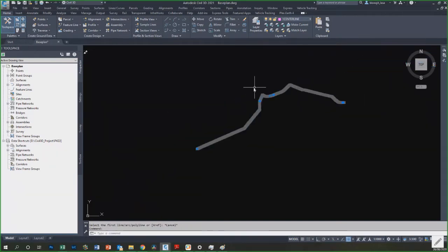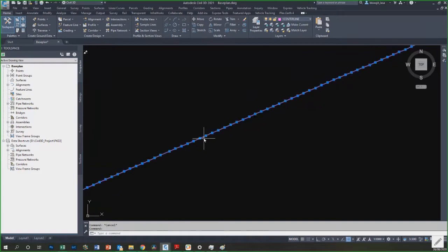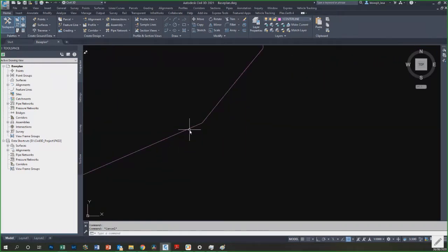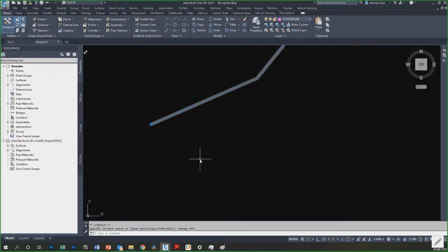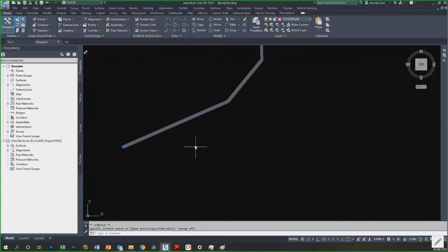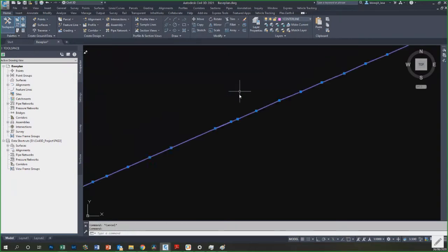So here comes the issue. Sometimes what happens is, the points which the surveyor gives, Civil 3D will not allow you to make it as a polyline or an alignment or something like that, a design parameter, for example. The reason being that this line somewhere must be containing a point which is self-crossing itself. What I mean to say is, these are the nodes. It must be having some points which are like this. You see, you cannot. AutoCAD will make this a polyline, but it will not take it as a design alignment because you have something which is like this one.